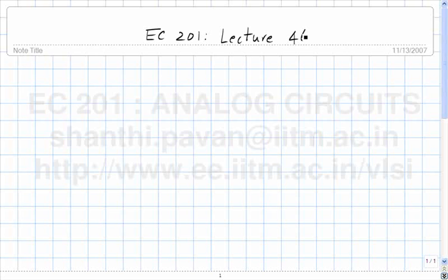You should never operate an operational amplifier without any DC negative feedback around it. An integrator operating open loop in a practical situation will result in the output of the op-amp either hitting the positive or the negative rail, depending on the sign of the offset delta V. And once it hits the positive or negative rail, the devices are all saturated or cut off, so the incremental gain of the amplifier is no longer the infinity that you thought it was. The entire assumption that the inverting terminal and the non-inverting terminal of the op-amp are at the same potential, all that is bust now.